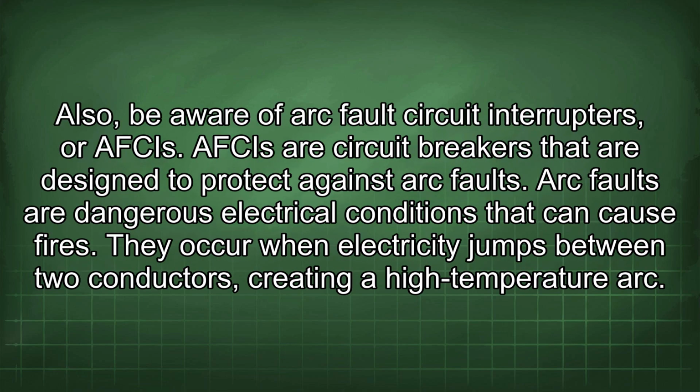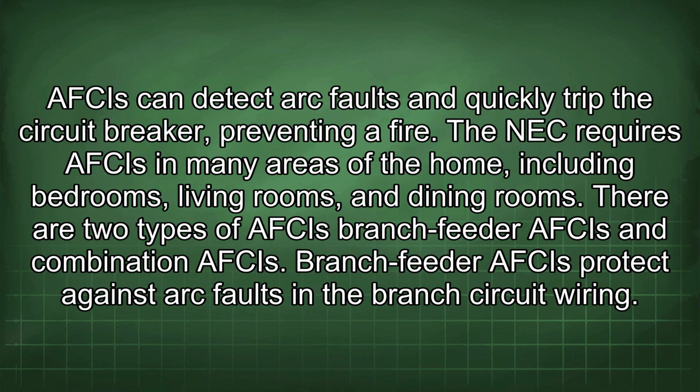Also, be aware of arc fault circuit interrupters, or AFCIs. AFCIs are circuit breakers that are designed to protect against arc faults. Arc faults are dangerous electrical conditions that can cause fires. They occur when electricity jumps between two conductors, creating a high-temperature arc. AFCIs can detect arc faults and quickly trip the circuit breaker, preventing a fire. The NEC requires AFCIs in many areas of the home, including bedrooms, living rooms, and dining rooms.